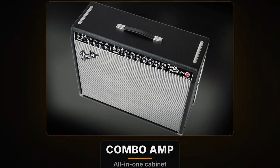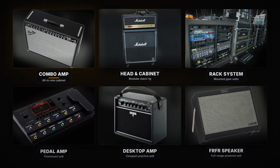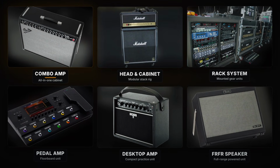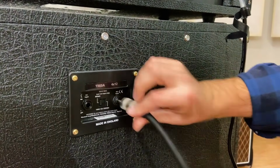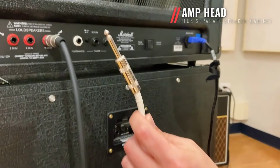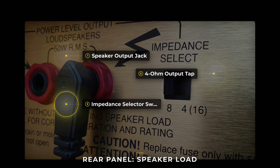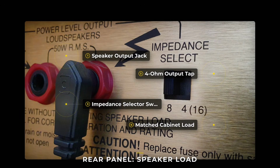A combo places the preamp, power amp, and speakers in one cabinet. It is easy to connect, though larger combos can be heavy. A head contains the amplifier electronics and connects to a separate speaker cabinet. This offers more flexibility, but the cabinet impedance must match the amp's supported load.